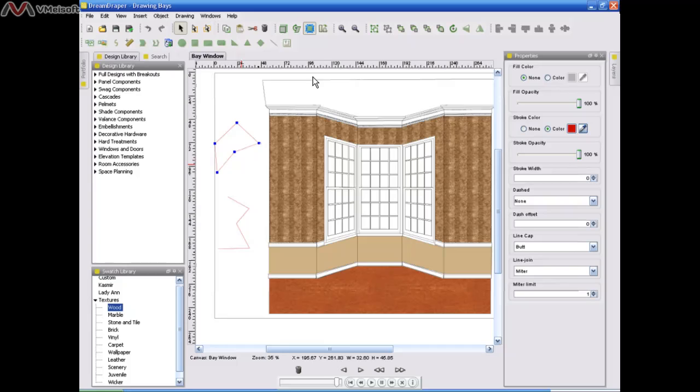And when you're done, just go back up to your top toolbar and go back to your normal scale icon, which is your default design mode. We have these other drawing shapes in our toolbar that you can experiment with, but the ones that I use a lot are the rectangle, the line, and both my polygon and polyline tools. I think you're going to find them very, very helpful when creating a room setting.